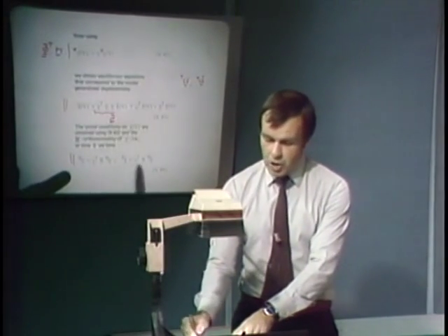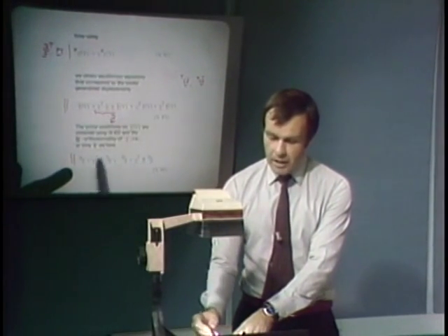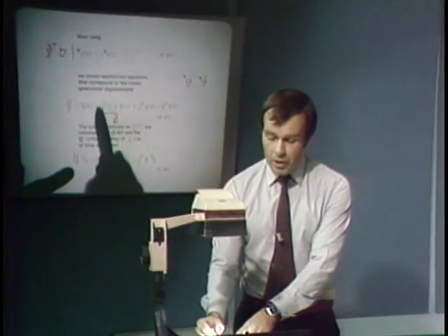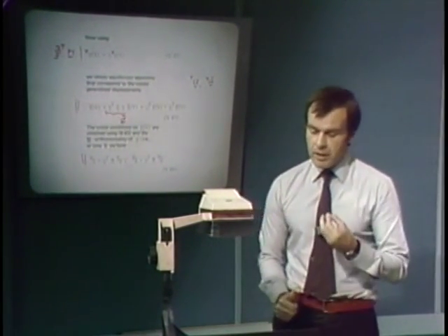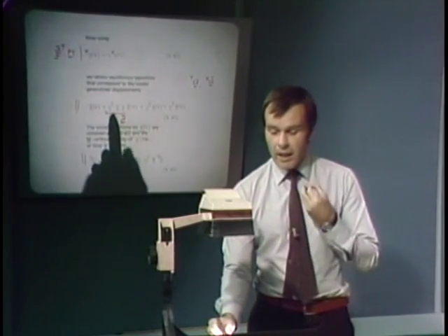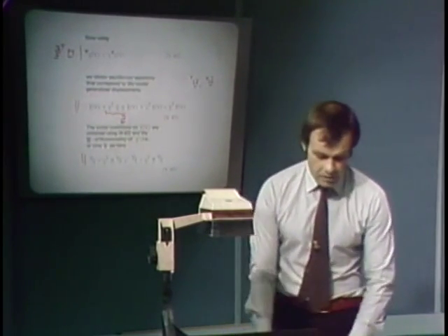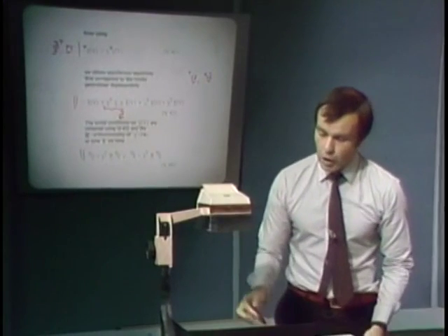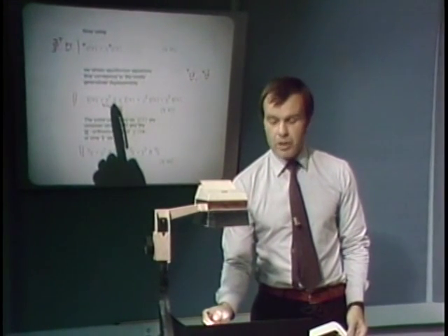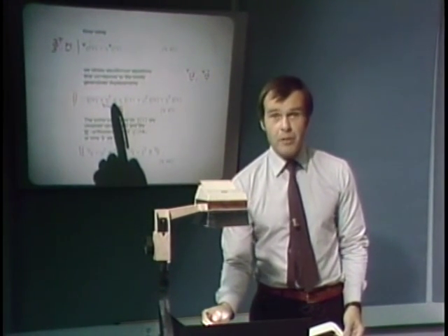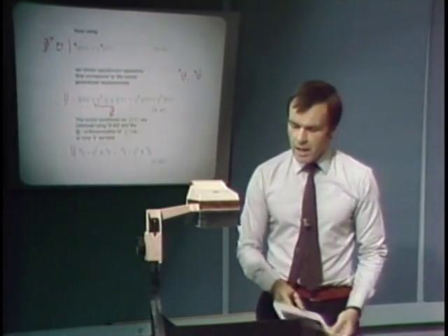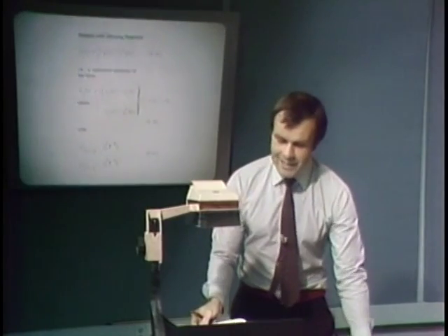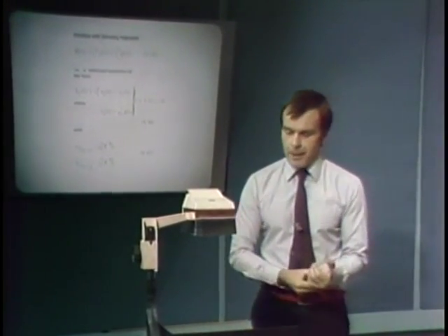Now, I should mention here that we still have to deal with the damping matrix. The damping matrix here needs particular attention. We do not have in general a diagonal matrix here, and we will want to construct specific damping matrices with which we can deal effectively, and yet, of course, these matrices must make physical sense. Let us look now, however, first at the case where we neglect damping.